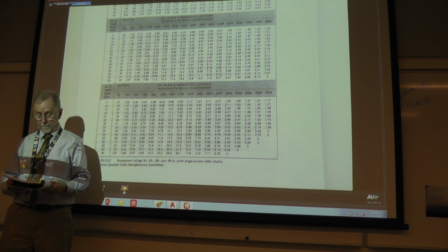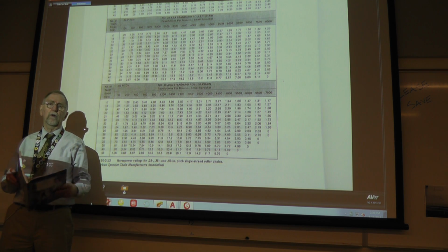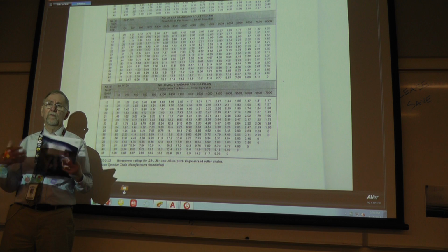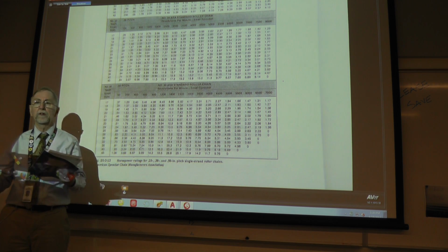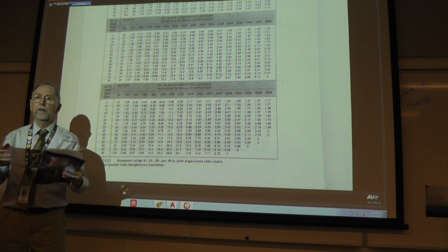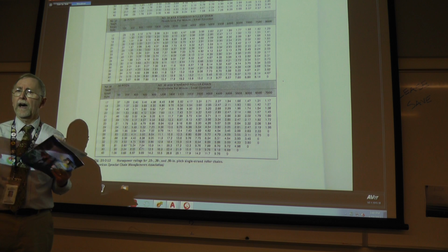Pierce. So for that first one, which was the service factor, the difference between the different service factors, that's kind of accounting for a higher horsepower? It's not accounting for a higher horsepower, it's accounting for the type of loading that's going on. Is it smooth, is there no interruption in it, there's not a jerky start and stop, or a lot of vibration or anything like that. It's more what kind of equipment it is.